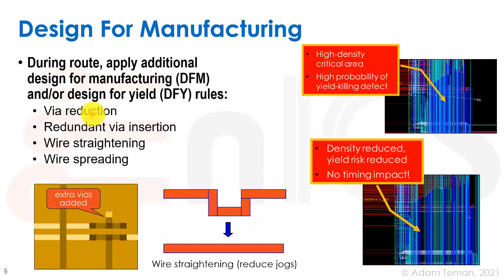So if we can get rid of vias as much as possible, that's really good. If we can stay within the same metal layer and not go up and down through a via stack, that's something that we want to do. And really, we can look at our final solution of our route and see if there are options to go and take vias and get rid of them.